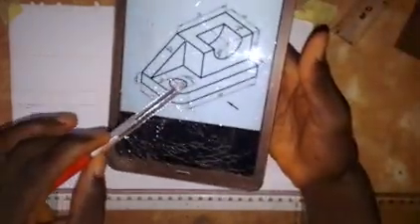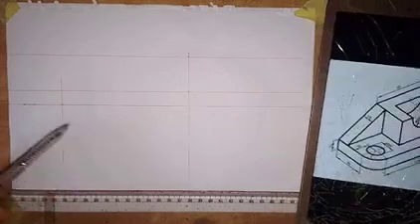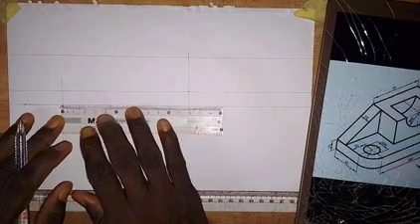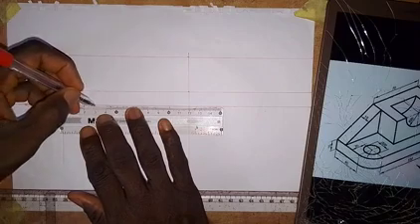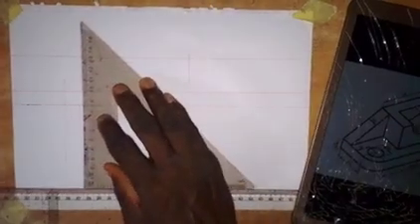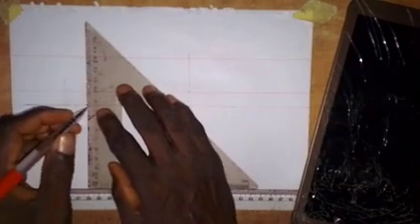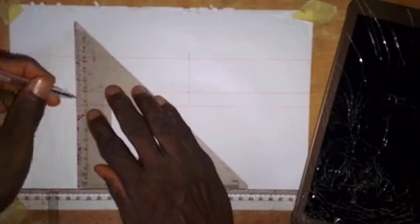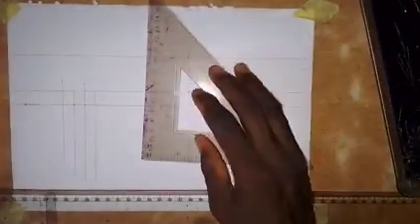The next thing that we are going to do, we have already drawn this rectangle. Let's put the hole inside. We take a measurement of 20 to locate the center of the hole, and then we take 10 to this side. We take 10 to this side because the diameter of the hole is 20 millimeters. So we draw this line as a center line. Here we draw this line, and then we also draw this line. So that's what we have there.